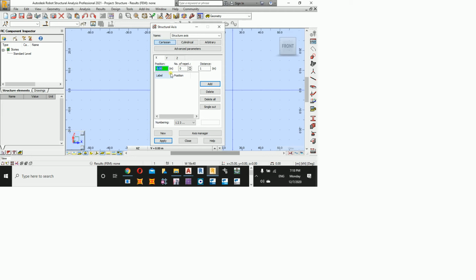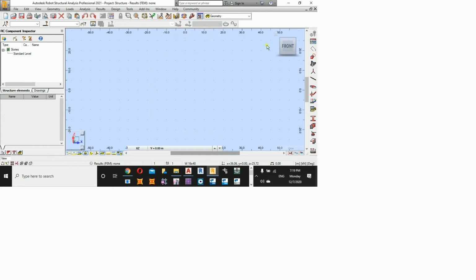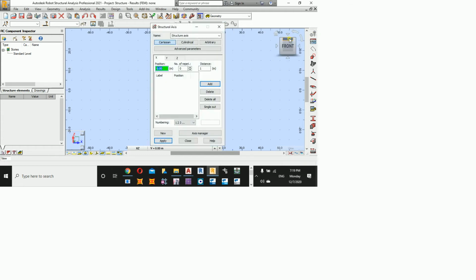So method number one, I can put 0. After 0 we have 2. After 2 I need to add 2 plus 1.25, 3.25. After 3.25 we have 1.5, so that's going to go 4.75. Okay, so what did I do? I calculated manually the coordinates in cumulative. Now, normally I don't recommend going for cumulative, because cumulative is good whenever you are talking about small elements or regular numbers without decimals. And that's not the case now.